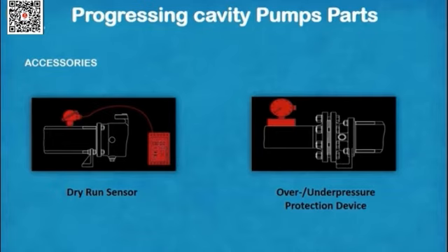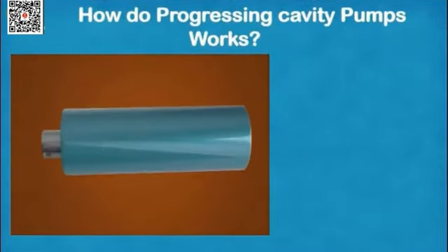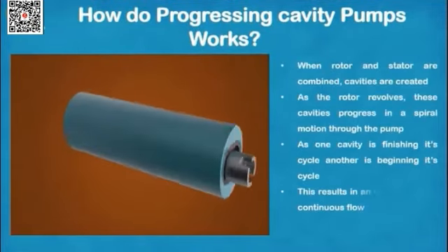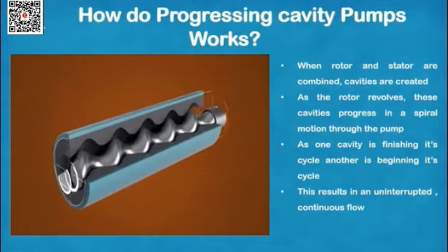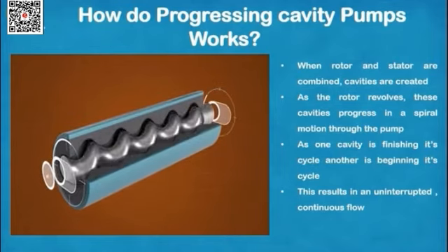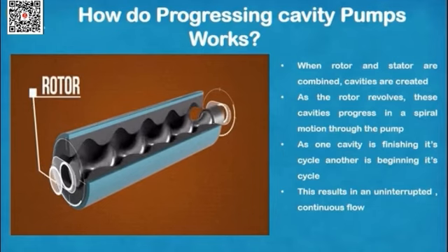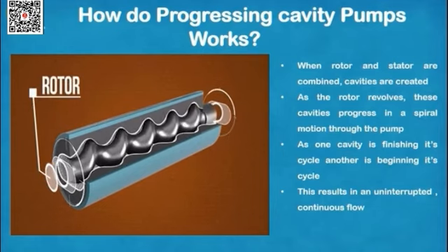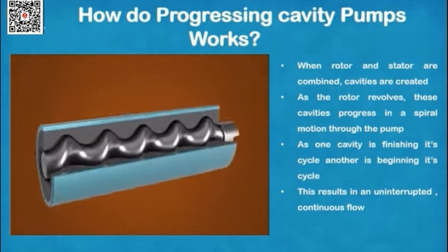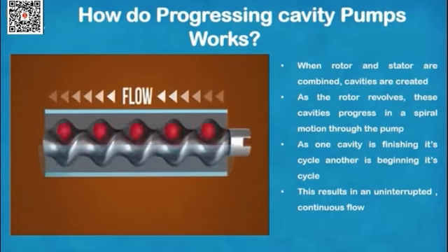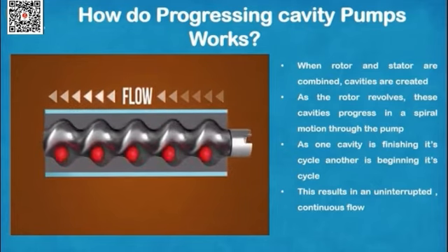Just like other positive displacement pumps, a progressive cavity pump is a flow-creating device. Let's take a look at how it works. The pump draws the fluid via the suction inlet and transports it into an elongated casing. Inside the casing are housed a helical rotor and stator. As the rotor turns, it touches the surface of the stator, leading to small cavities forming. The fluid then flows progressively through this series of cavities until it is expelled via a discharge outlet. The pump moves the displaced fluid at a constant speed, regardless of the inlet pressure.